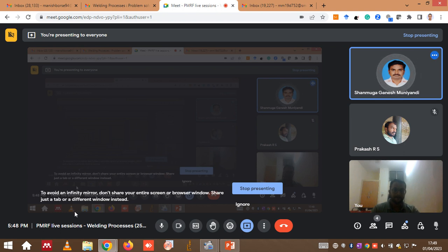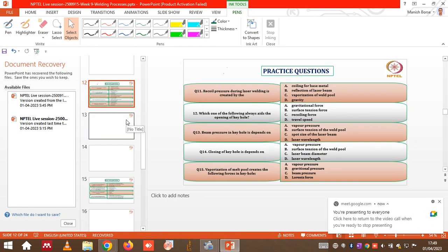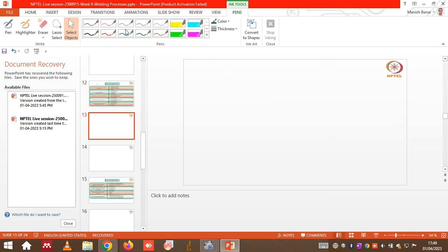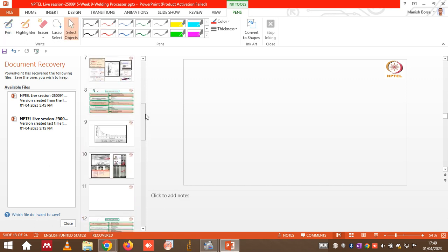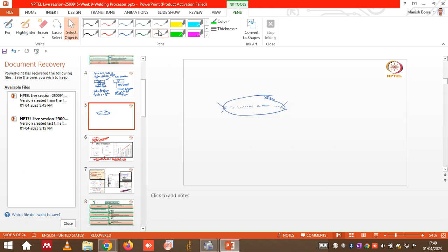No, so solidification stresses are always generated during the solidification, but this kind of behavior will only be seen in certain materials, which have a composition far from the eutectic composition. So it is not only restricted to the aluminum alloys.